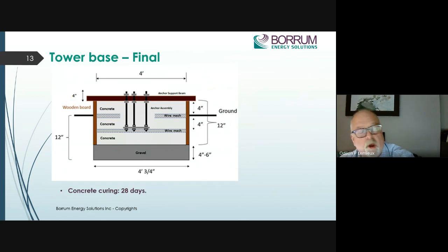It's not the weight of the tower. Once the tower is up, the weight on that concrete pad is not that significant. What we found is that when the tower is horizontal and you start raising it between 0 and 5 degrees, the shear forces on that base are very, very high.